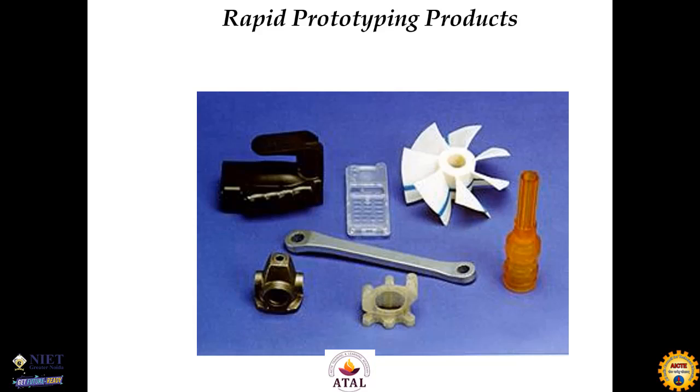welding technology, like TIG, tungsten inert gas welding, MIG, or cold metal transfer. The CMT is very useful. This is the new technology of Fronius. The CMT technology is used for this BAM process. So by this BAM process, we can create large components in less time and less cost